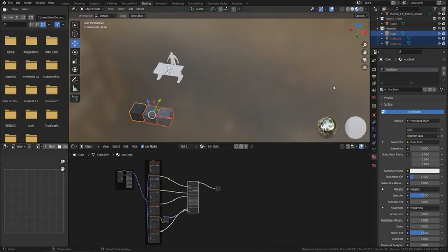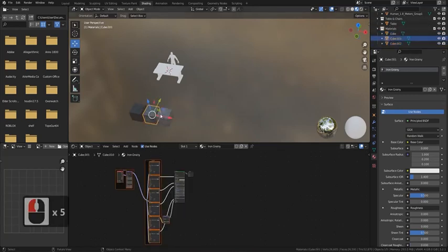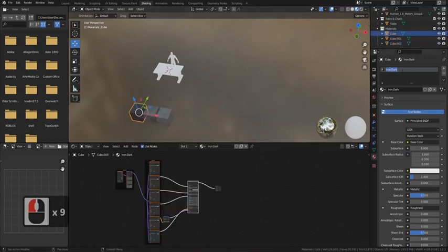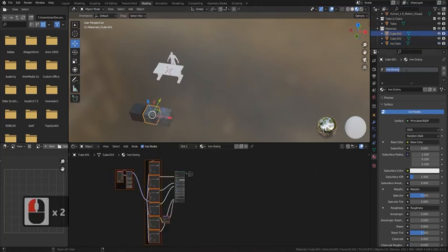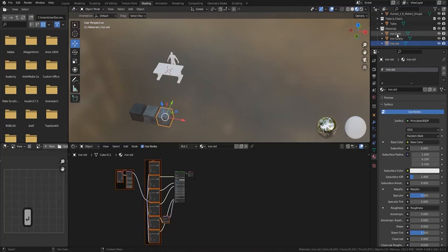Now, anytime we alter a material, it is going to alter these anyway. The other thing is you might as well name your materials because at the moment, it might be hard for you to go down them. So all you need to do is double click this one, for instance, press Control V and just rename them like so. It just makes it a little bit easier to actually get along with this. So Control V, and finally this one, double click it, Control C, and double click this one, Control V, and there we go.